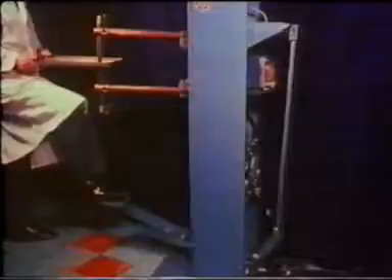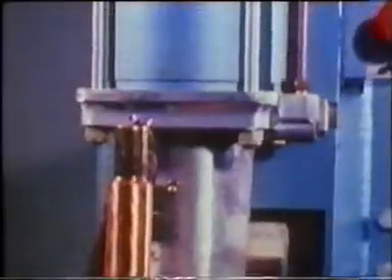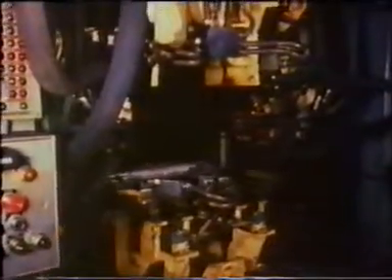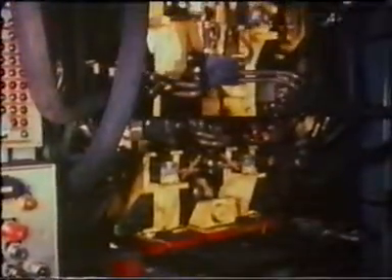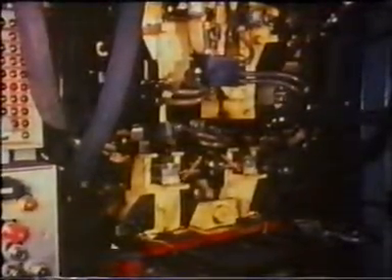Pressure, or electrode force, can be applied in several ways. Here, it's applied by the operator, who uses a foot pedal with a linkage mechanism. But sustained high production is best served either by air cylinder pressure, which is easily controlled by electrically operated valves, or by hydraulic cylinder, which gives the highest pressures and is used principally for multi-spot welding machines, where many cylinders have to be grouped in a small area.